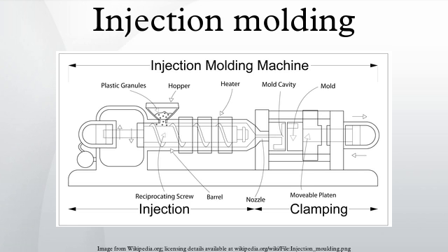The sprue bushing is to seal tightly against the nozzle of the injection barrel of the molding machine and to allow molten plastic to flow from the barrel into the mold, also known as the cavity. The sprue bushing directs the molten plastic to the cavity images through channels that are machined into the faces of the A and B plates. These channels allow plastic to run along them, so they are referred to as runners. The molten plastic flows through the runner and enters one or more specialized gates and into the cavity geometry to